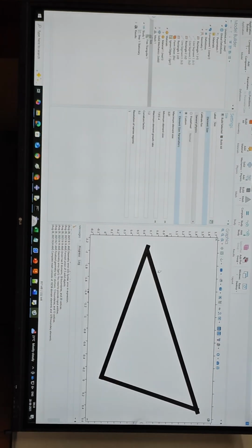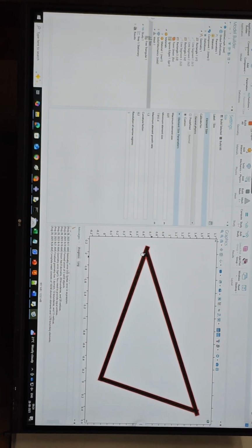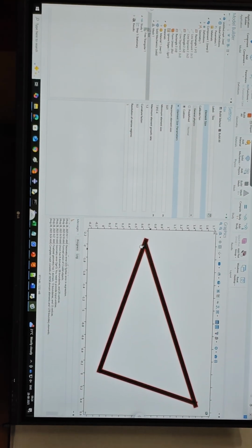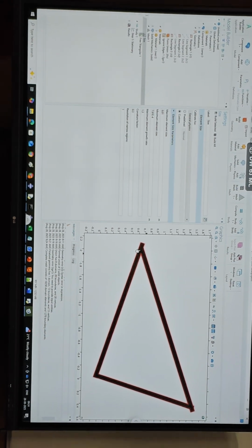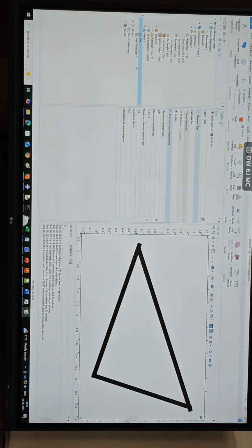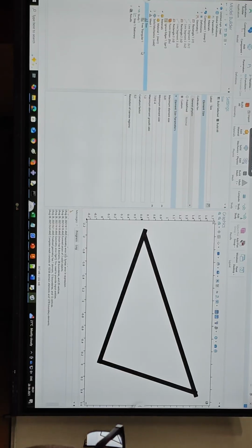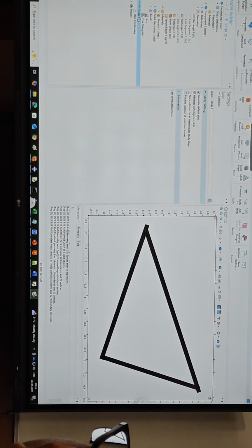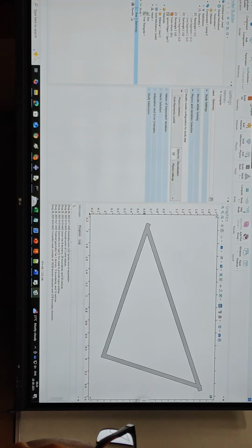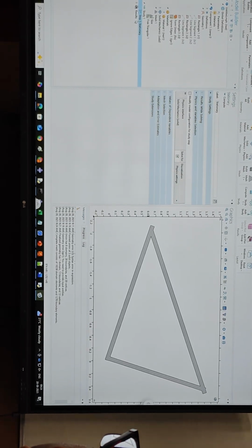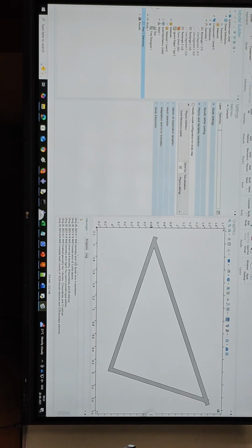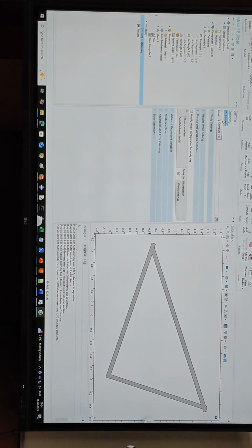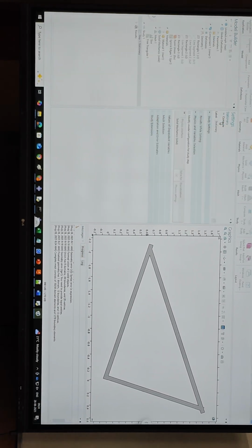Now you have it pretty dense, the mesh. Right? Don't worry about it. It's a linear analysis using a direct solver. Your mesh density is not a big deal here. It'll solve within seconds. Then we come to study. So now in study you don't have to change anything here because you're not using any geometric nonlinearity. The basic license doesn't have it. So all you have to do is just click this little button here, compute. That's it.